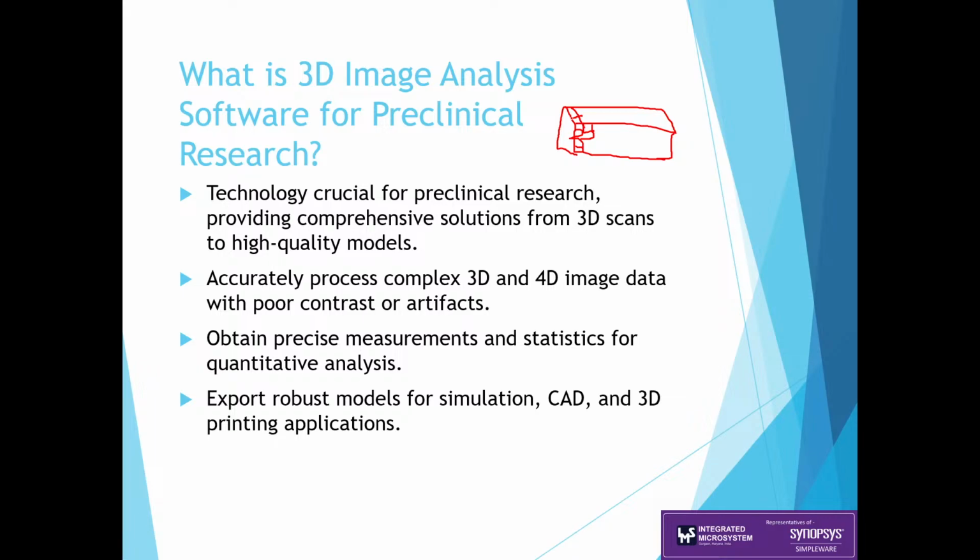A stack of images matters because when we are doing segmentation on a single image, we get a 2D image analysis out of that. But if we have a stack of images, that is, multiple images aligned in a single view, we can do the 3D volume consideration. And apart from that, Simpleware software also has 4D image dataset support. So even if the dataset has a time offset value, that too can be segmented across the